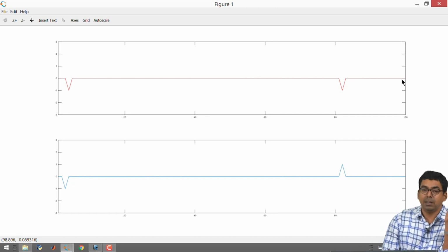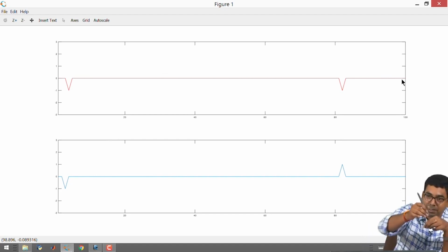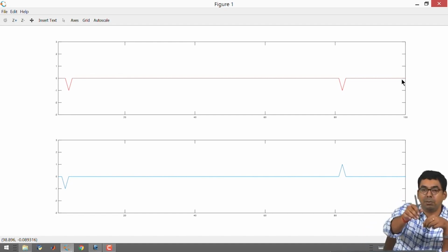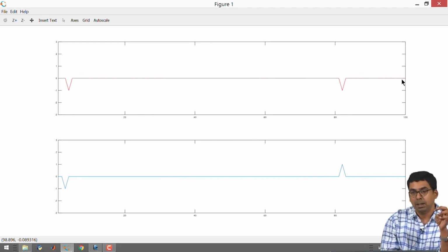We also know that the velocity in the transmission line is going to be equal to u. So you take the time at which you sent the pulse, calculate the amount of time it takes to receive the first echo, figure out how much distance it traveled two ways, and then figure out the location of the fault. So it gives you the location of the fault and the kind of fault that has occurred. The same thing can be done for the short circuit also. This method of finding a fault in a transmission line is known as time domain reflectometry. All you are doing is launching a pulse, waiting for the reflection, and then trying to figure out what the reflection can tell you.